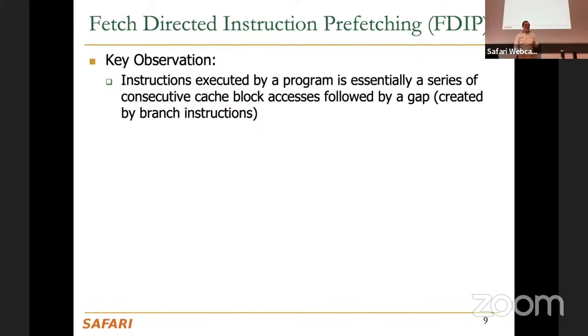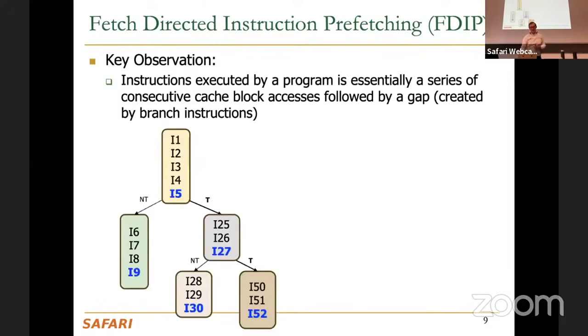So we already do that actually with branch prediction, right? Branch prediction already does that. So the idea over here is to run the front end of the machine faster, and prefetch the instructions to a queue. While the back end of the machine is stalled, you can keep prefetching instructions to this queue, and you can keep predicting. So the idea is really decoupling the front end of the machine and the back end of the machine. The back end of the machine can be stalled for many reasons, as we have discussed, memory, for example. But the front end of the machine can keep going almost forever.